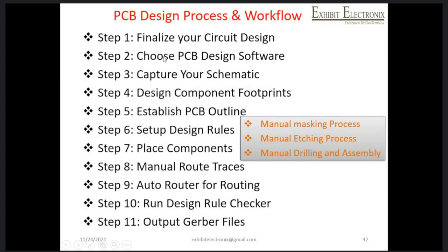Capturing a schematic and designing the component footprint: footprint is a very important term. In layout, we have 3-pin ICs, 4-pin ICs, 8-pin discrete ICs. Some have pins on both sides, and some have pins on only a single side, that is SIP, single inline package, versus dual inline package. ICs like LM358 and 555 are dual inline package ICs. Some ICs like LM317 or LM7805 regulator ICs have pins on only one side. Those are single inline packages.